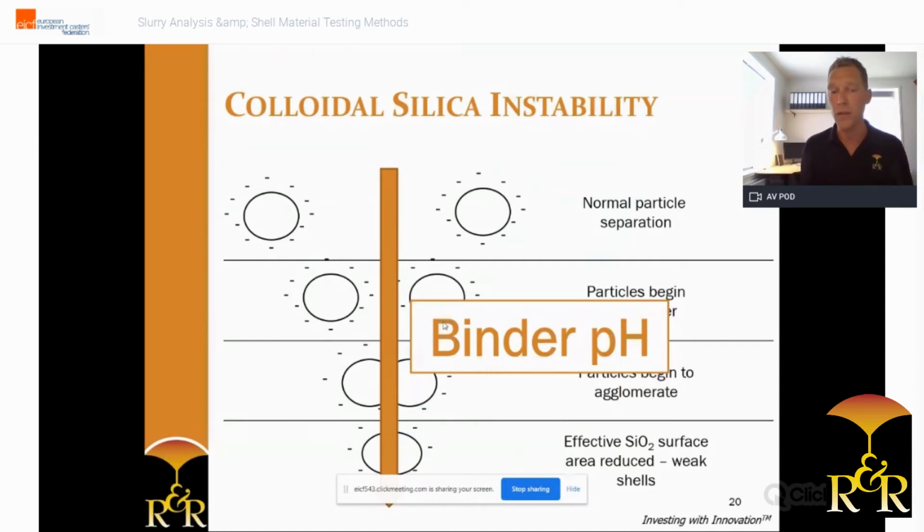Because once the binder is irreversibly damaged, you need to replace the slurry. And replacing the slurry is already expensive, but at that point you will probably also see a lot of cast quality issues, which is, I think, maybe in some cases even more expensive than replacing a slurry tank.